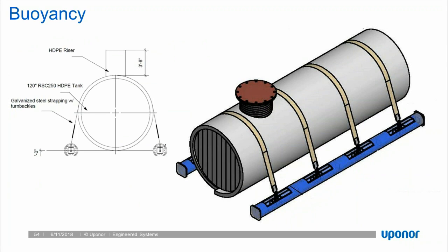Sometimes the contractor is not interested in sourcing a strap and anchor system or doing cast-in-place or precast. We can provide wheel anchors, which is essentially the same concept. The cross section of that tube is the cross-sectional area under the horizontal that provides the horizontal projection under the vertical soil load, and the cross section of that tube is what counteracts the vertical force up with the soil column above it. The advantage of this system is it's completely prefabricated.